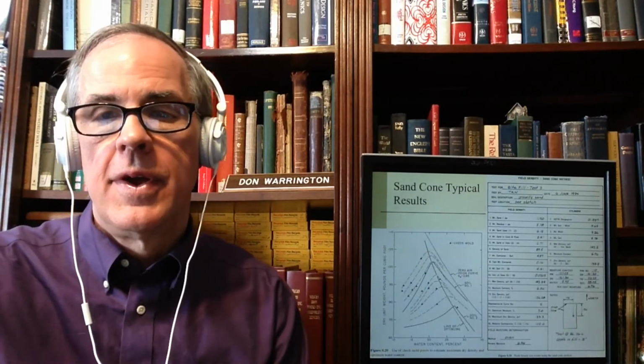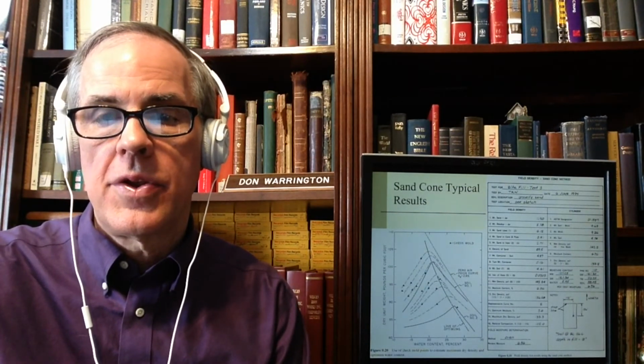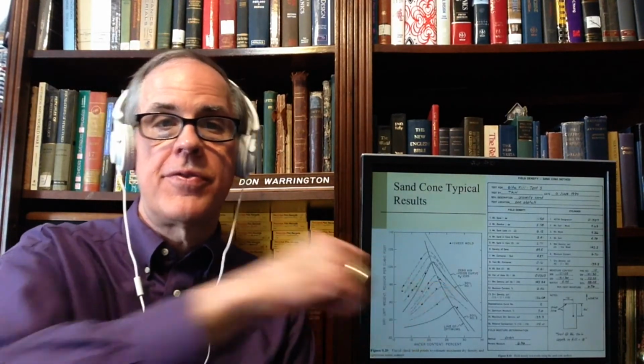I'm not going to go into a lot of detail other than to say, first of all, you can use check mold points to estimate your maximum dry density. You obviously check them in the lab and in the field and see if they line up. And also, this is a data sheet for the sand cone test as well.